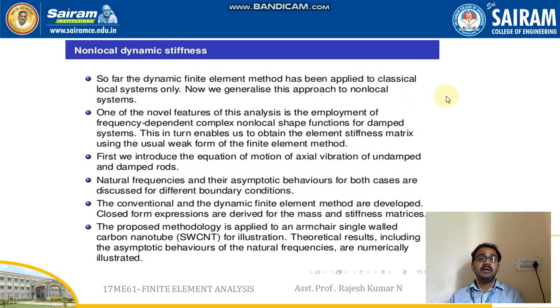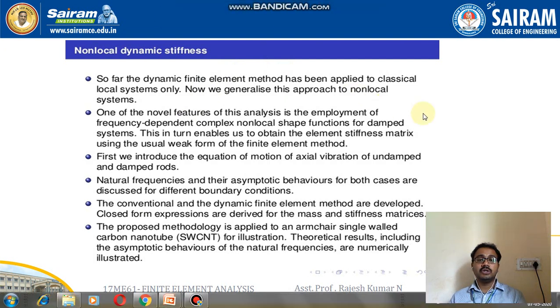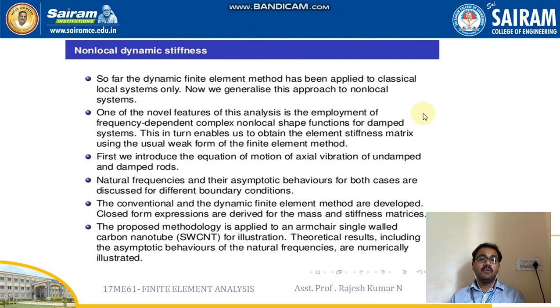So far, the dynamic finite element method has been applied to classical local systems only. Now, we generalize this approach to non-local systems. One of the novel features of this analysis is the employment of frequency-dependent complex non-local shape functions for damped systems. This in turn enables us to obtain the element stiffness matrix using the usual weak form of the finite element method. First, we introduce the equation of motion of axial vibration of undamped and damped rods.